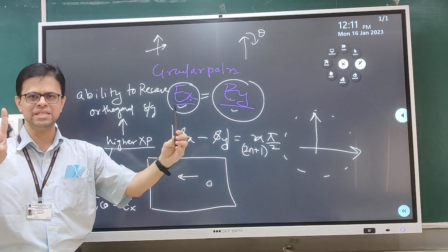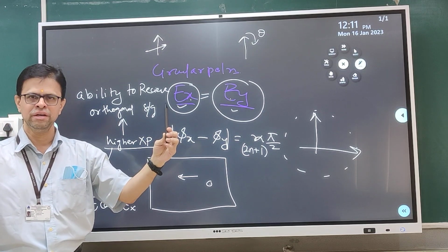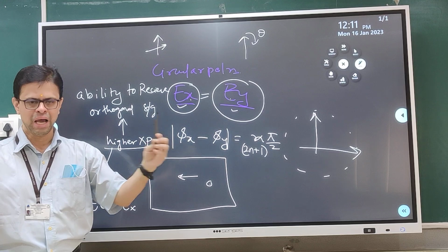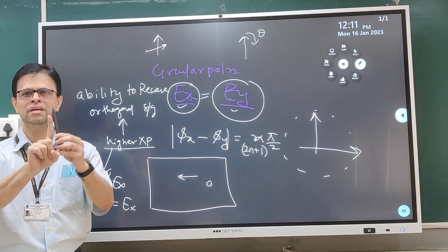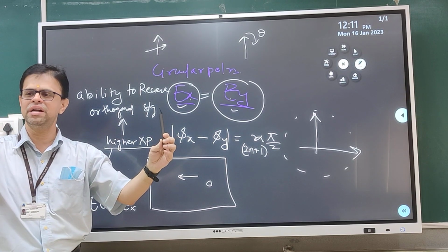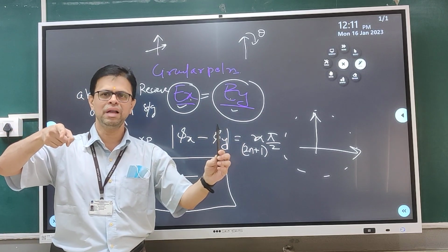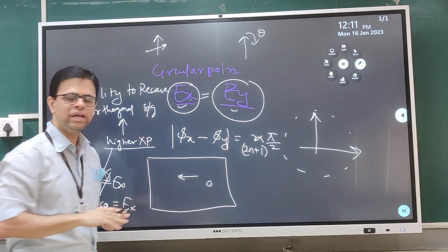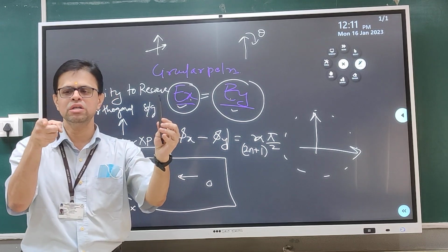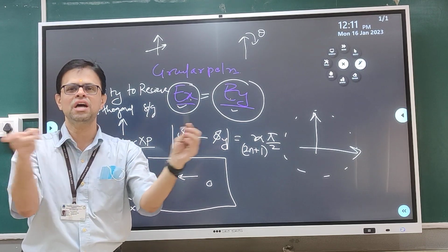In these two cases, both the dipoles are there, their planes are matched, I will get a proper signal. But if I keep the receiver dipole orthogonal, then what will happen? I will not get a signal. Why? Because the two polarizations are mismatched.